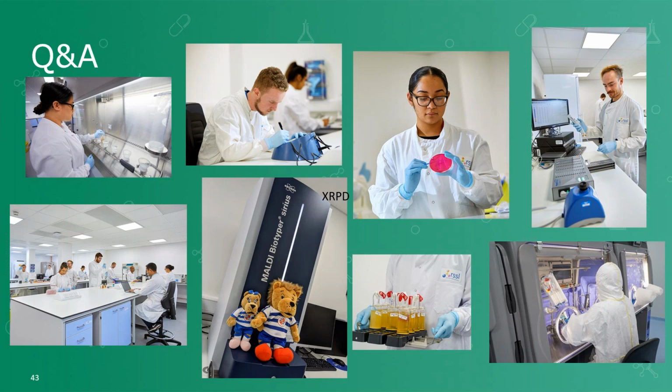Okay, right. I have a question from Christopher who says, so how do we ensure that we have good flow of water to minimize biofilm formation without causing turbulence, which can cause biofilm formation? Well, it's odd actually. It's sometimes water that's too laminar as well that can also pose quite a risk.